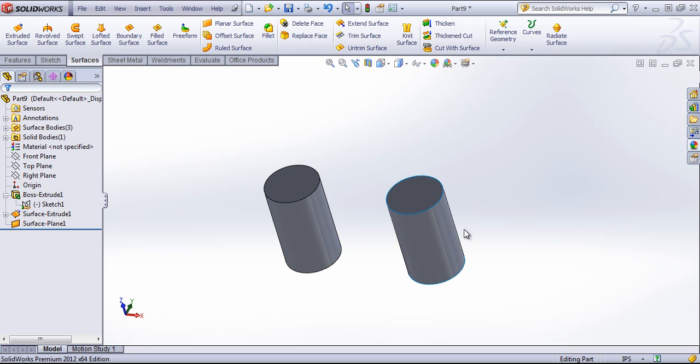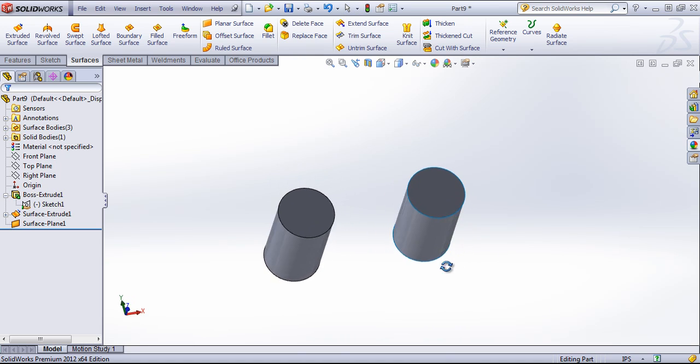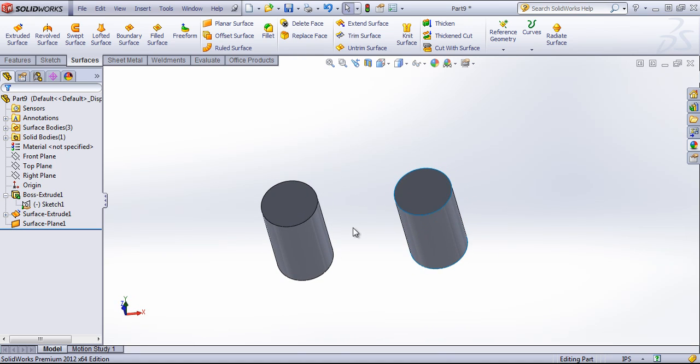So whether you're working with a solid model or a surface model, SolidWorks is pretty much always looking at the external surfaces. Each edge is a boundary between two surfaces. So if you ever get that error that you have a zero thickness geometry, SolidWorks is seeing too many faces connecting at a single edge, so it has issues developing that geometry.